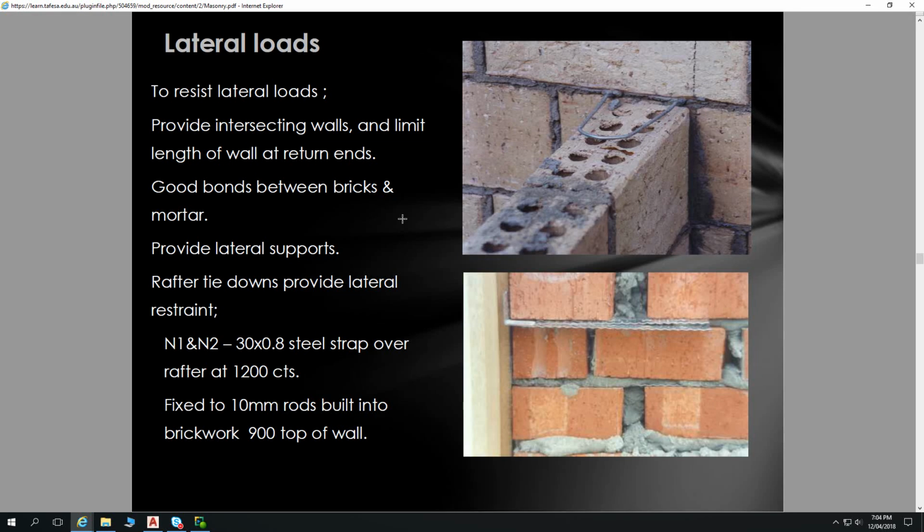If we had just a ribbon plate on the top of that and then some masonry anchors into our top course of brickwork, what can happen there is we just take off the top course of brickwork, and that can happen fairly easily. So that's, I don't know, 20 kilos worth in comparison to like 120 kilos worth in there, just estimates. Is that done while you're in the cavity? So that's done across the cavity.